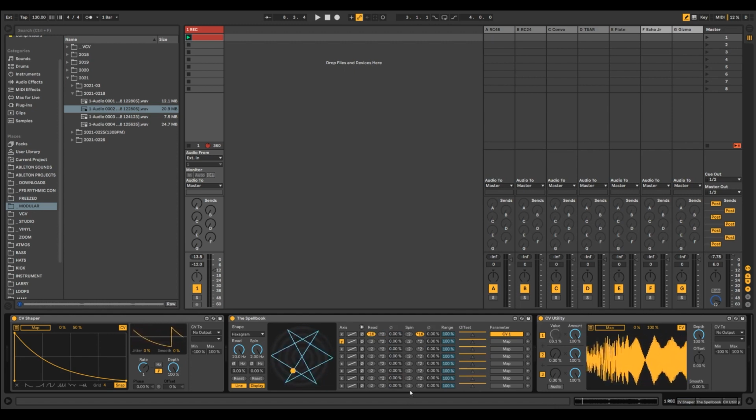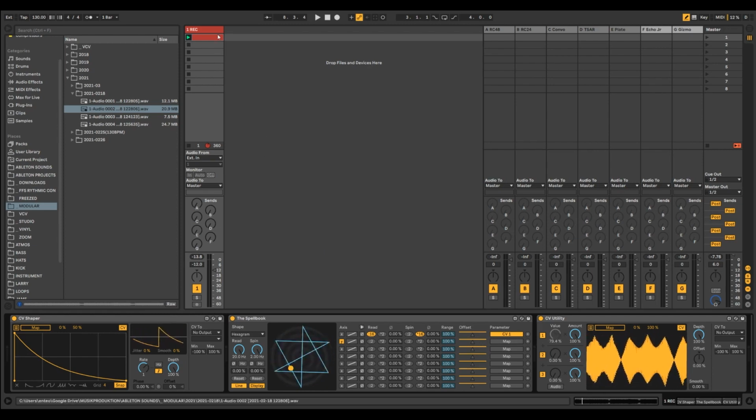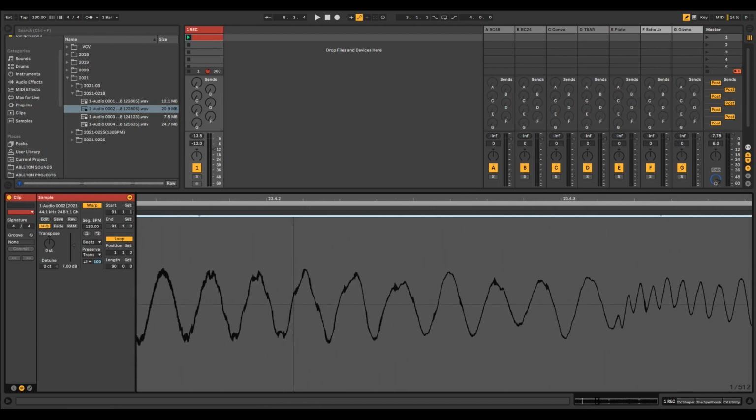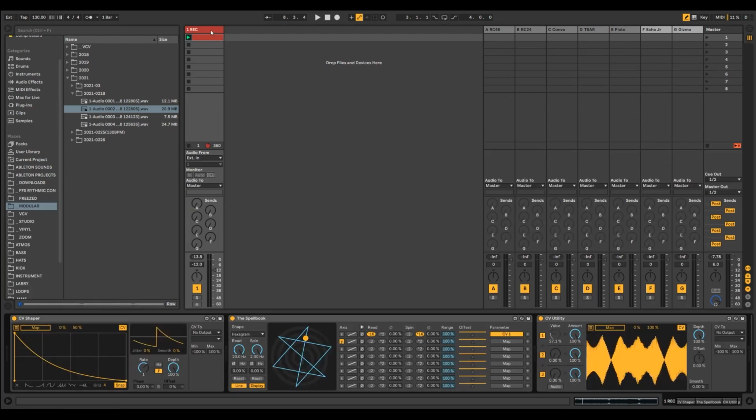And basically now I'm sending control voltage to this one. I'm sending a kind of digitalized representation of CV here. So basically this is the building block of synthesis, and this is the art of synthesis. It's how you combine voltages into sound, because sound is voltage. It's very rapidly oscillating voltage, and then we're using different types of voltage to control these oscillations, right?